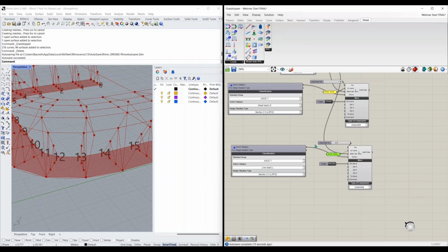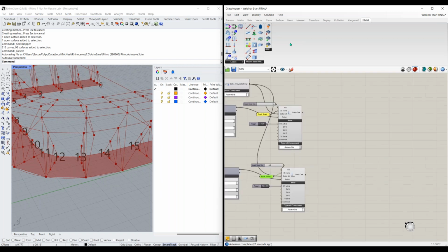And now we need to go over load combinations. So when it comes to load combinations, I can just drag down here a load combination component, and we need to define a number, or actually the load case number or the index number for load combinations isn't really too important because we don't use load combinations anywhere else in our information here. So it's not too important to reference. The combination name is also not too important. What we really need to focus on immediately is the design situation.